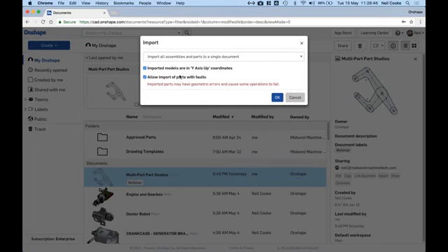You might find data that's in IGES format, which is very old, please don't use it, or it comes from Creo, Pro Engineer, or some other obscure CAD systems, you might find that there are gaps in the surfaces. So if you leave that unchecked, Onshape will just ignore it.